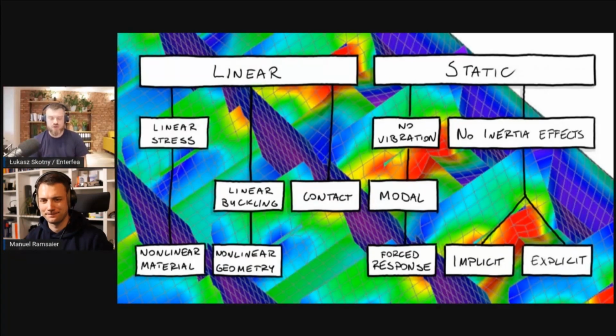Yeah. And for imperfections, when it comes to buckling, there are rules. Vague as they are, there are rules that allow you to have a guideline, to guesstimate what the imperfections might be. Right. Here, you are on your own, and this is more important. So it's a difficult thing. So if you're close, better build it and test it. I think that's a good tip. Tell this to the guy who's designing the skyscraper. Right? For a skyscraper, that's maybe not possible, but.